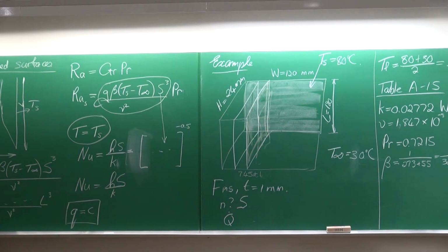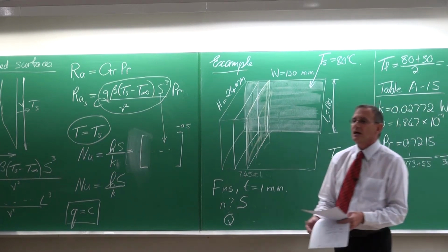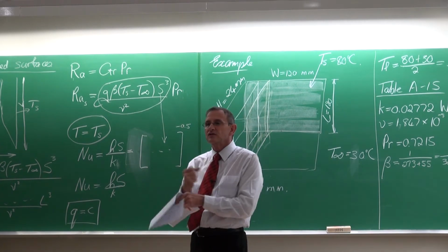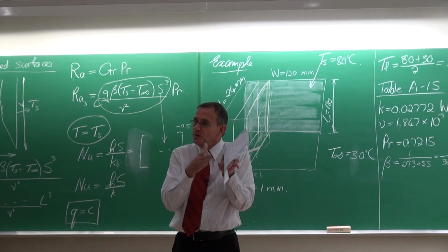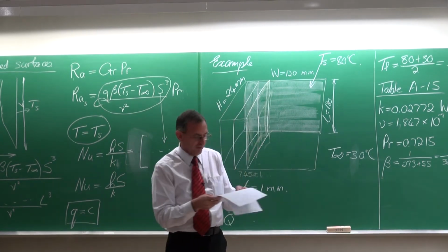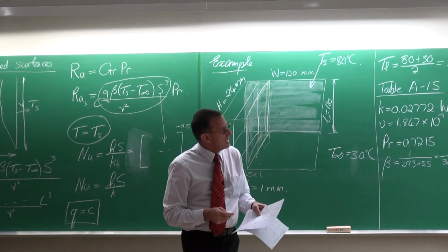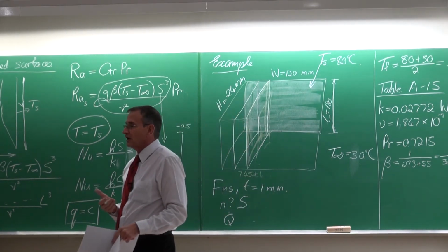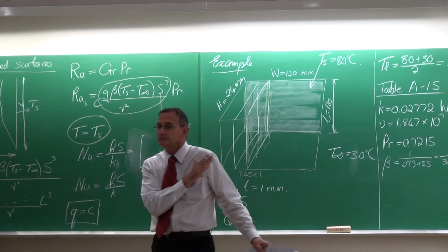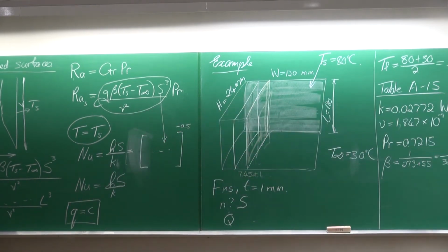We cannot use 0.8 of a fin, so we are going to use, in this case, no, sorry, I keep on making a mistake. So, sorry, this is 13 point something, one or other value larger than 0.5, so we're going to use 14 fins on that surface. And that would give the optimum heat transfer rate that we can get out of that area using the optimum spacing of the number of fins. So if you go onto that area and you put in 28 fins, the heat transfer rate will be lower than this value. So we also have to calculate the heat transfer rate.